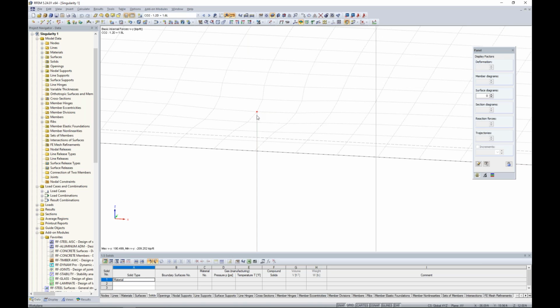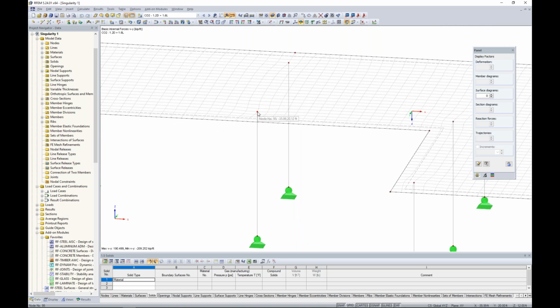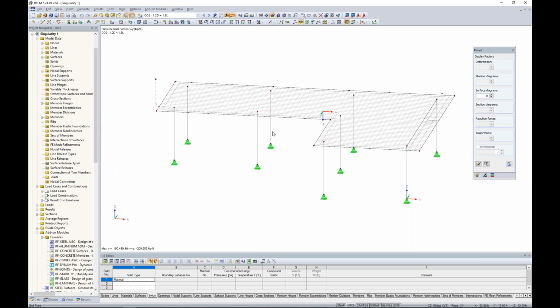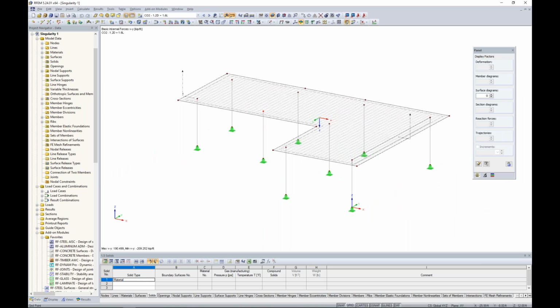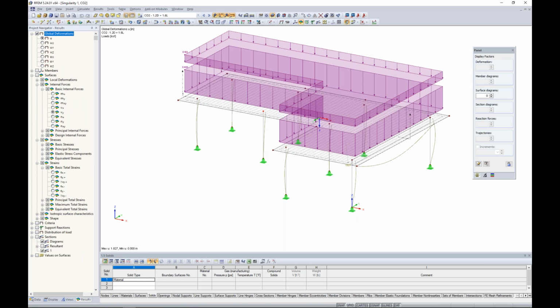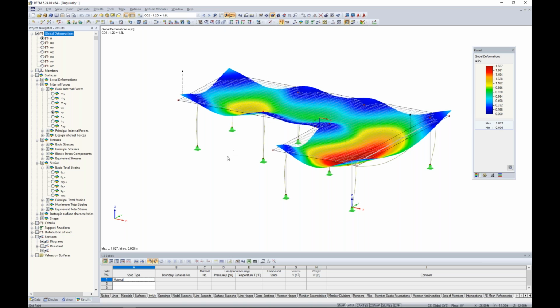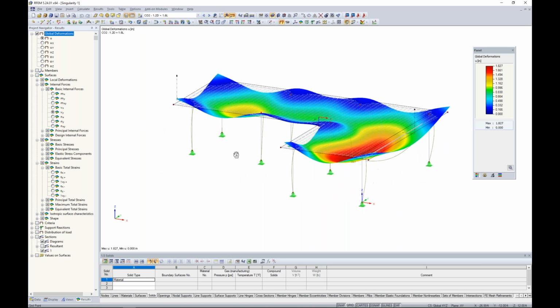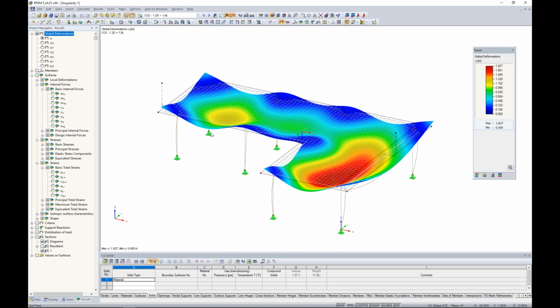So all of the force transfer is taking place at this single FE mesh point, and this is a result of why we get singularities where we don't have really load distribution. So you can see for this example, what I've done is I've applied a couple gravity loads here for dead load and live load. And if we run the analysis, which I've already done in this case, and we take a look at our results, we'll turn on our ISO bands, turn off our loads. Well, okay, the initial deflection, nothing too strange here. But let's take a look at the internal forces for our slab element.